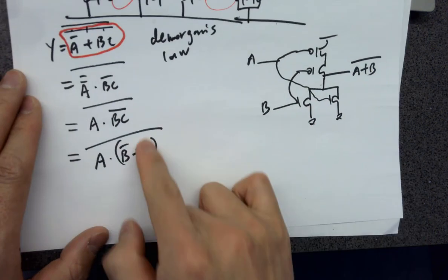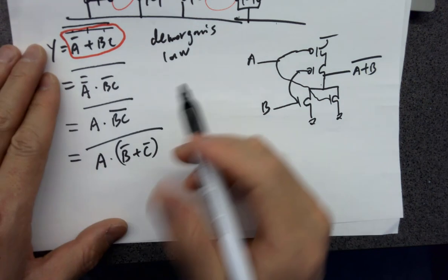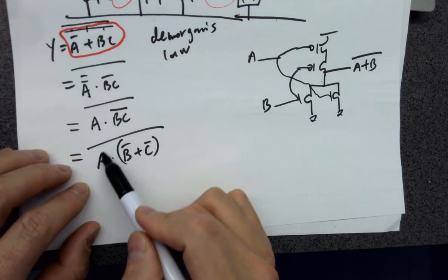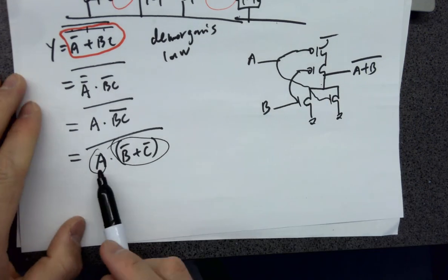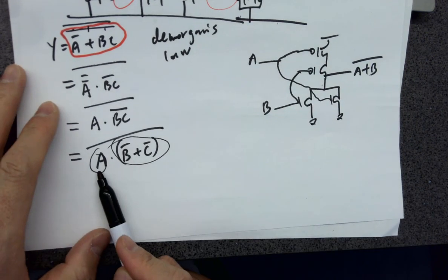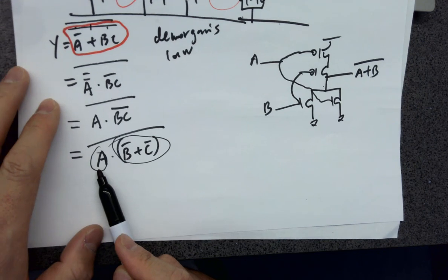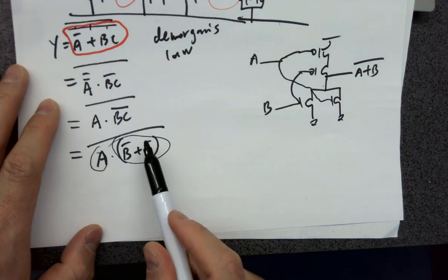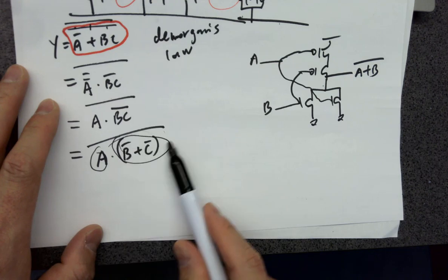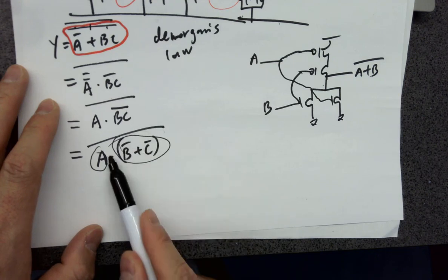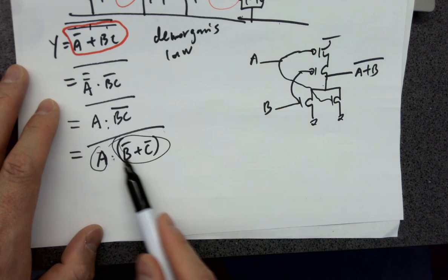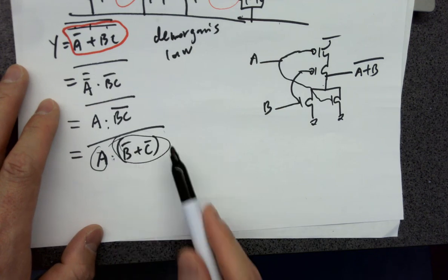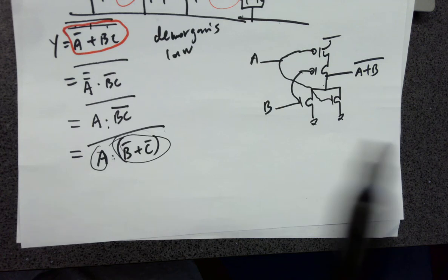So in that case, by looking at this one, if we treat this one as a big box, the A signal's PMOS transistor should be in parallel or series with this box. It's a non-logic. It's an AND, not. So the A signal and this whole thing need to be in parallel for PMOS.